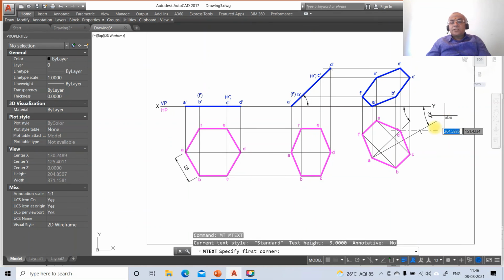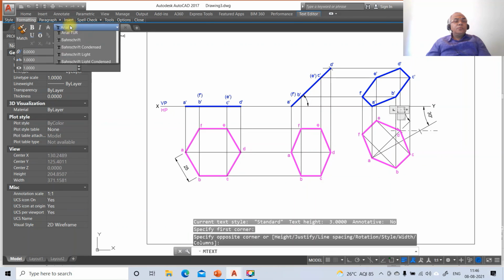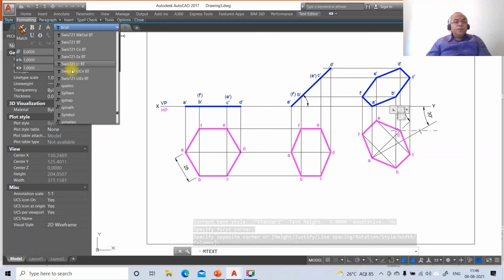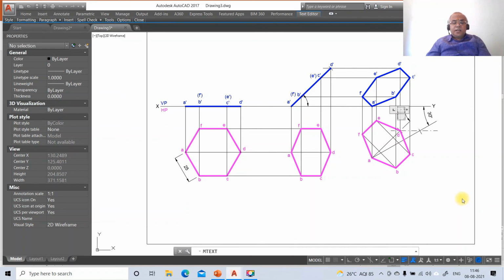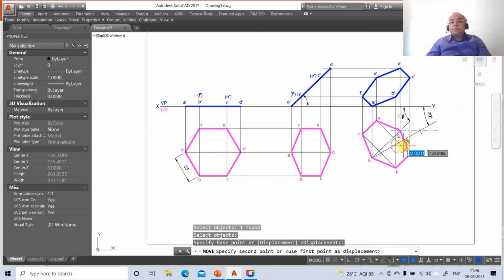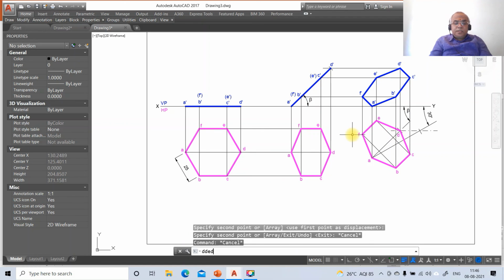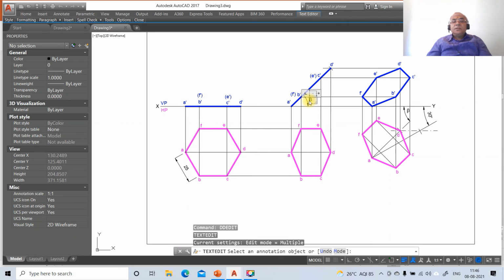Now you just go to M text, select this entire thing, and go to formatting, go to symbol, so make this angle as beta, and click here, then go to move, select this and place it wherever you want. Similarly, you want to copy this, so copy this here, and you make a DD edit, select this, and you make this as small letter theta.